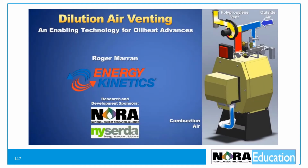Hi, I'm Roger Marin, presenting on dilution air venting as an enabling technology for oil heat advances. Dilution air venting is a proven technology which has been used with gas water heaters for decades and with oil heat boilers since 2011. As can be seen in the venting animation, dilution air reduces venting temperature to enable higher efficiency, cost-effective, and desirable venting options for oil heat where an existing chimney is not adequate.